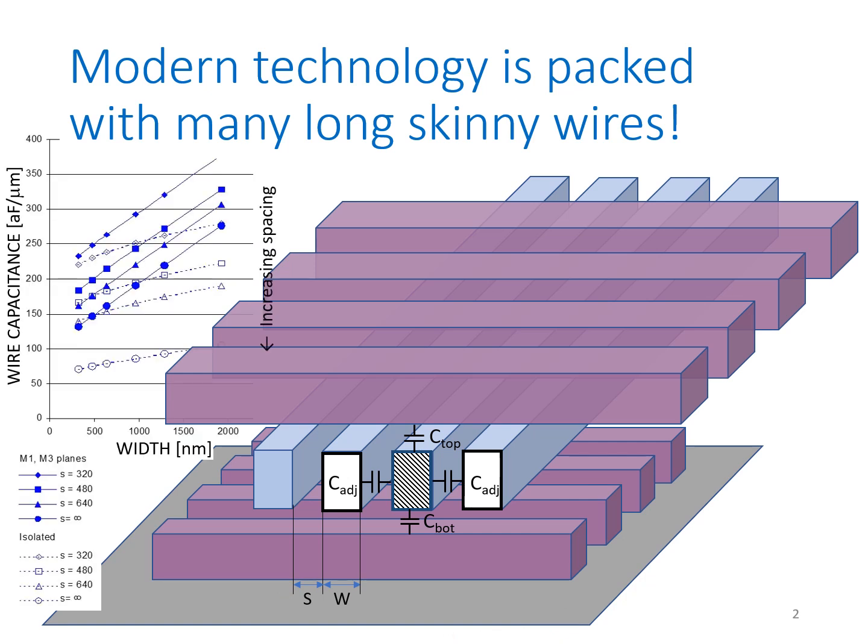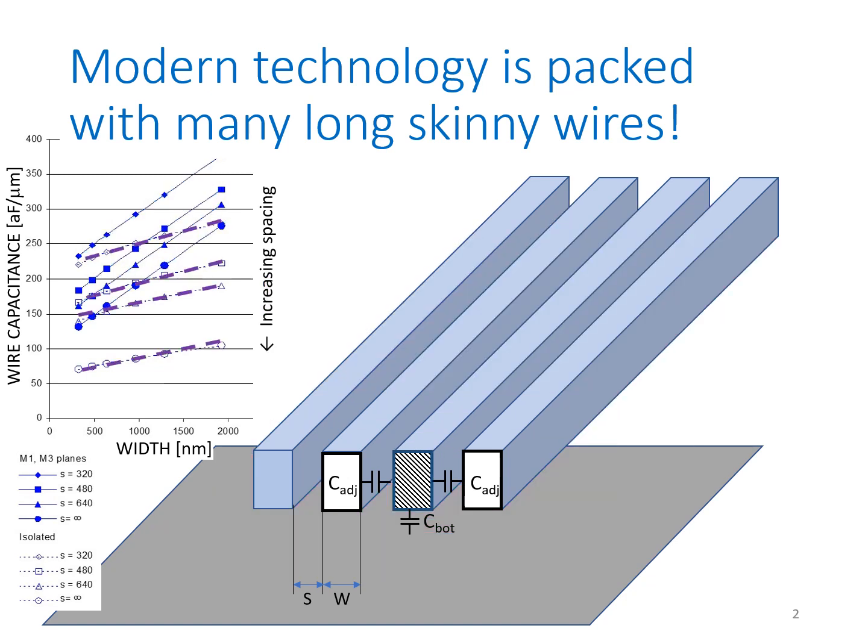Wire capacitance is strongly dependent on the width of the wire and on the spacing to sideway neighbors. The bottom part of the graph, the dashed part, is for an isolated wire with no wiring on top and no wiring below. Now we can see that the wire capacitance depends more on the spacing than on the wire width, indicating that the sidewall capacitances are not negligible.